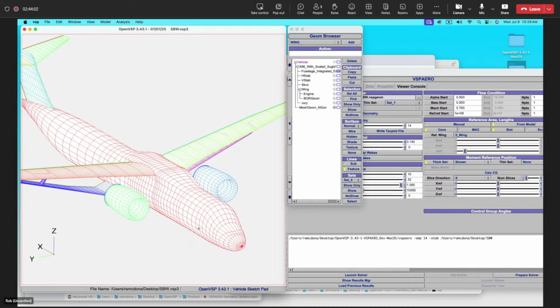Yeah, so I see Andy asked, why might you want to do a mixed thick and thin model? That's a great question. What I find is, number one, the thin solution is faster than the thick solution. You have half as many panels on lifting surfaces. Also, a trailing edge, by definition, has a top and bottom panel that are very close together, and that can cause issues in the solution and in the solver. By going to a thin surface, you get rid of those.